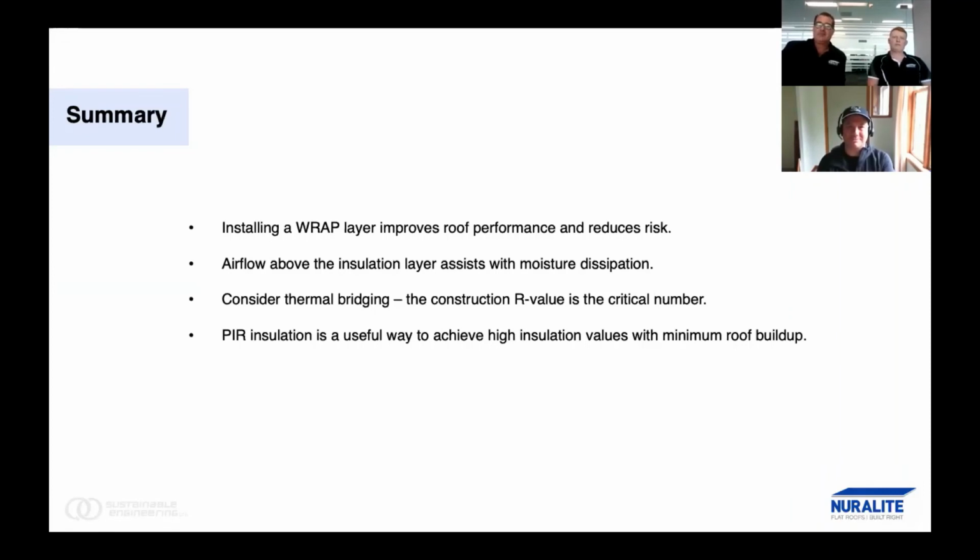And I guess nothing is as airtight or as vapor tight as an aluminium foil layer. It's true, nothing's as vapor tight. But there are a lot of fully adhered membranes that would be suitable for that application, it just depends on the roofing material and everything else. I think that's the reason why your potato chips come in a foil bag now, not a plastic one that's taped together.